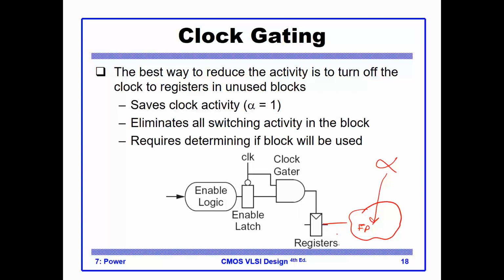Well, suppose I notice that these registers are active when I'm doing integer execution in my CPU. So this floating point unit is active unnecessarily. So what do I need to do? To make it quiet, I have to keep those registers unchanged, not switching, keep them quiet.